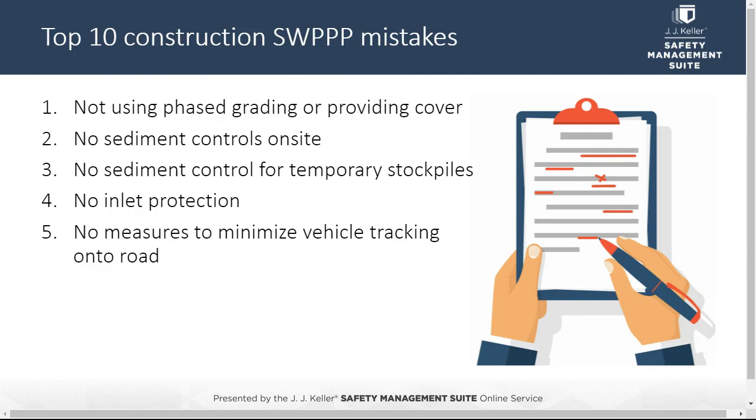Number 4, missing or lack of stormwater inlet protection. So all storm drains that could receive a discharge from the construction site must be protected before construction begins, and these protections must be maintained until the site is finally stabilized.